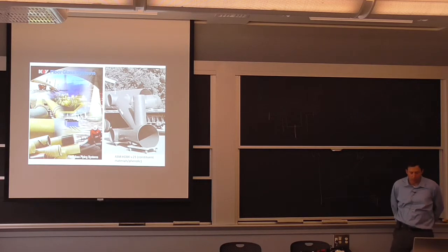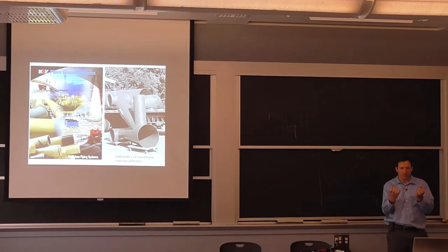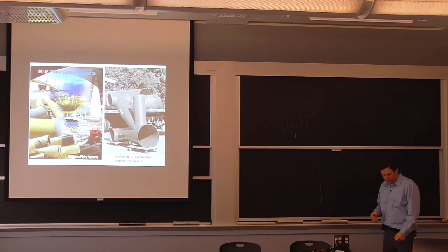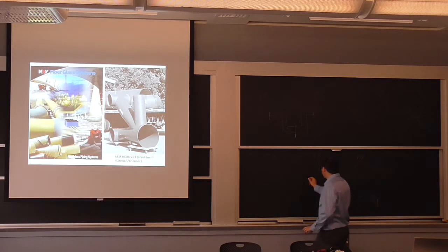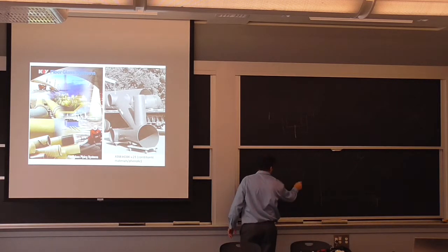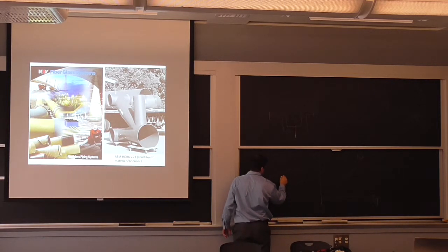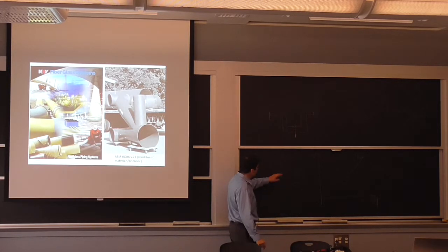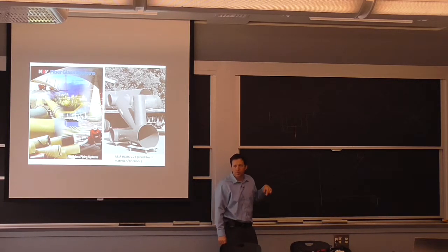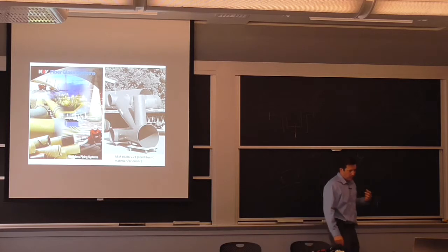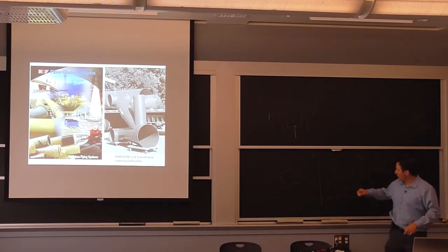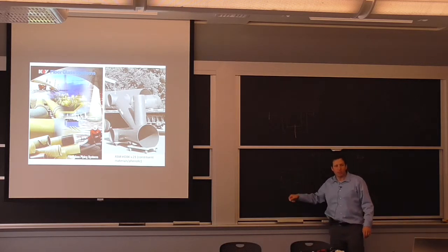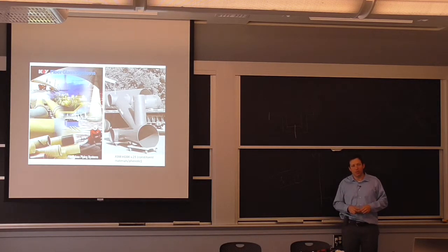And that's how a lot of industrial composites work, so here you have pipe. If you remember pipe when we were talking about it, we said one problem with the unreinforced pipe is, say I just had it here, my hoop stress, so the stress going this way, for pressure. So there's pressure inside. My stresses are twice as much around the circumference than they are in the longitudinal direction. So one way for an industrial composite to work is you wind the reinforcement around the pipe, because that's really where you want the increase in strength.